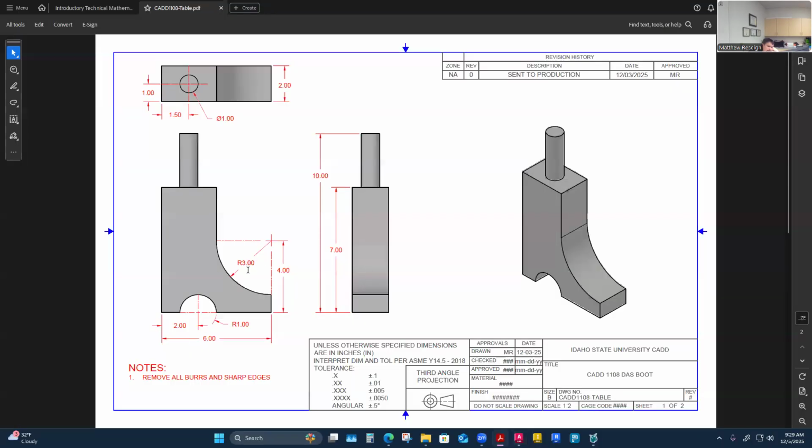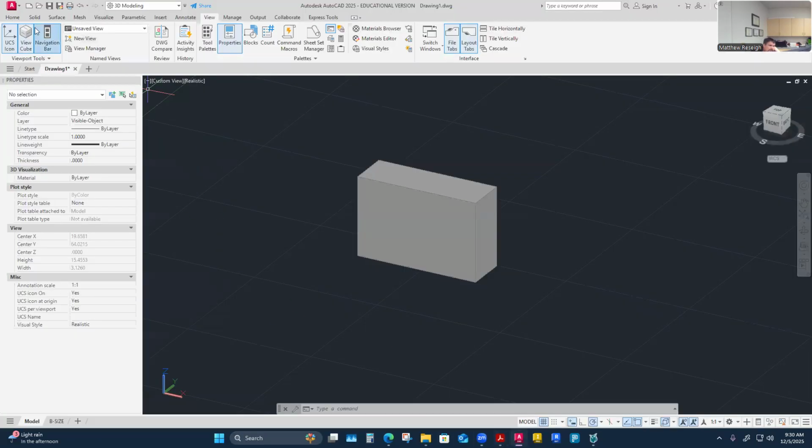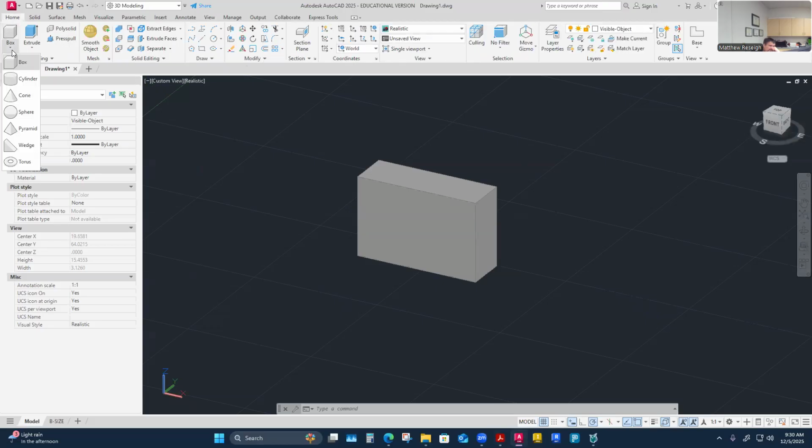So what I'm looking to do is find where the center of this circle is. I'm going to use this circle as a cutting device, kind of like a trim device like we would use sometimes. So this is a radius of 3, and the center point of the circle is the center of that edge of my box that I just drew, my 6 by 4 inch box. I'm going to be able to place my circle using those 3D object snaps right on the corner of my box. So how this works, which is kind of weird, is if I'm on my home tab and I want to draw a cylinder, I'm going to use the shape command to do this cut actually.